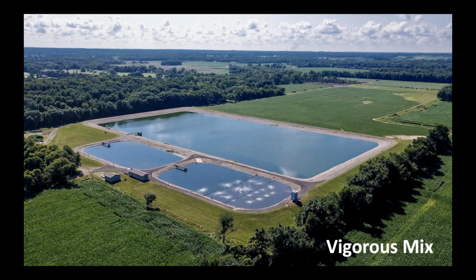The third type, and this is actually our favorite, not our favorite, but kind of partly created by Triple Point, is what we call vigorous mix. If you have partial mix on one end, you have complete mix on the other side, and the middle is what's called vigorous mix, which is not quite partial mix, not quite complete mix. This is just a little bit more mixing. It can be really useful if you have an existing partial mix lagoon that you want to create more treatment capacity in, because you do get faster treatment with vigorous mix.